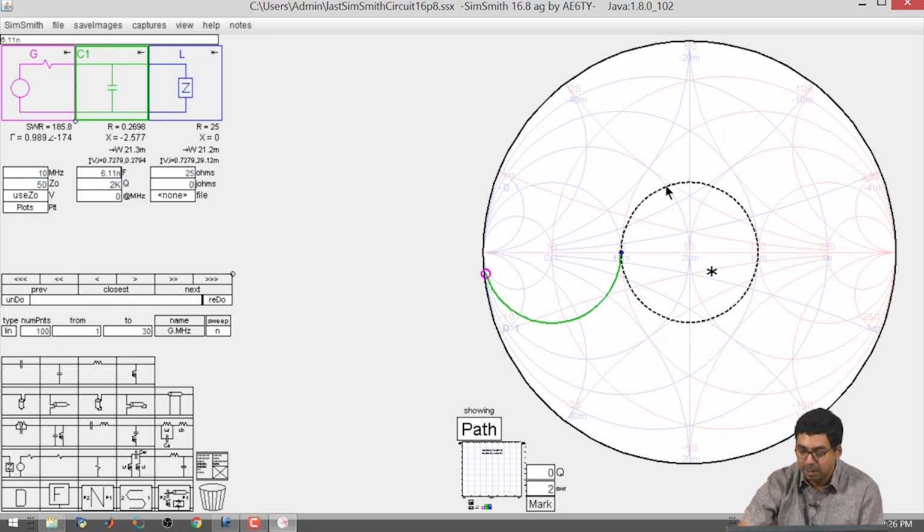The goal is always to come to the middle of the Smith chart, and there are two circles which are intersecting corresponding to R equal to 0 or G equal to 0. Both of them pass through the center of the Smith chart. On top of that, X also is equal to 0, the horizontal axis. So, you have to arrive here. You have to reach one of these 2 points and arrive at X equal to 0. This is going to be the objective.